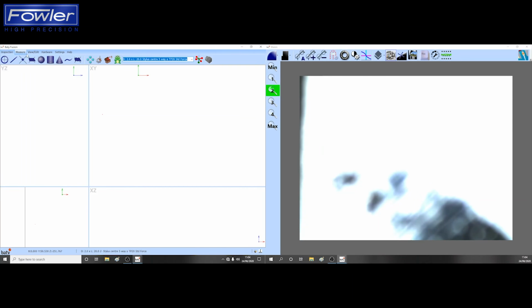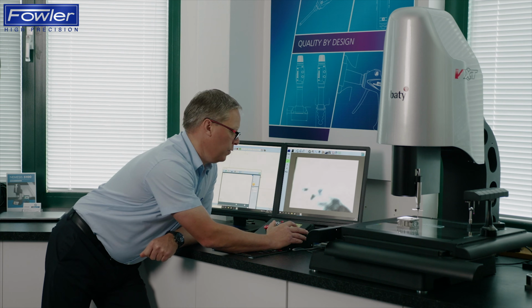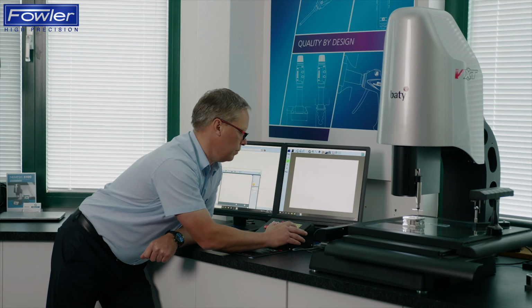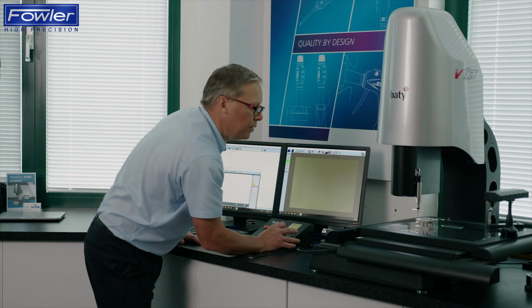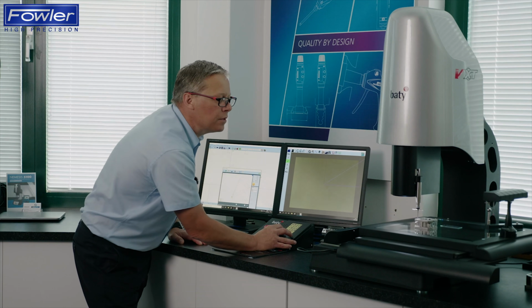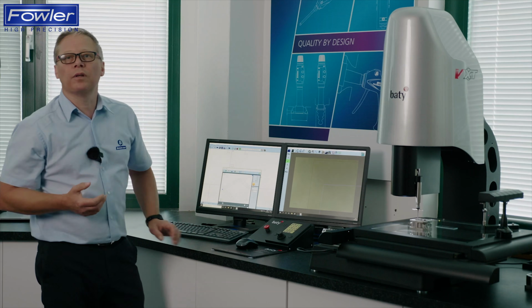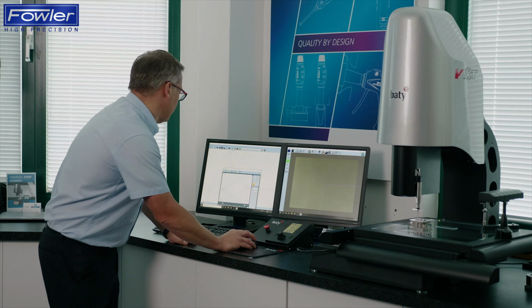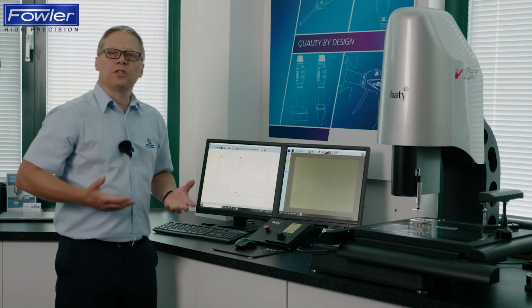I'm going to call a plane on this new inspection, and using the new touchscreen probe moves screen, I can simply ask for a probe move in the Z- direction. So you can see how easy it is now for me to make these probe moves using one touch on the screen. I get a nice CNC controlled, speed regulated touch probe move, very safe. I'm going to call that a reference feature and move on and measure some more features.